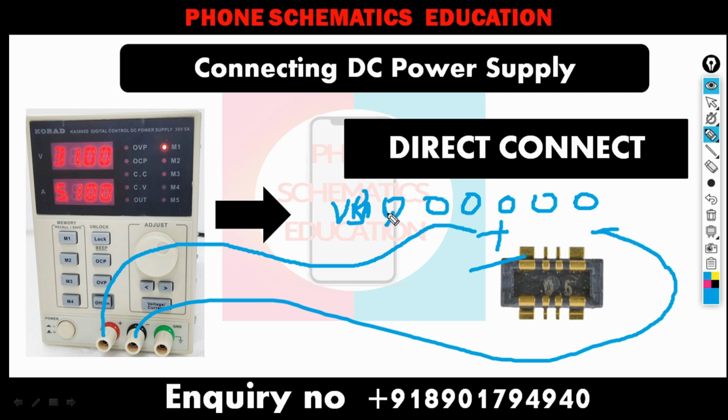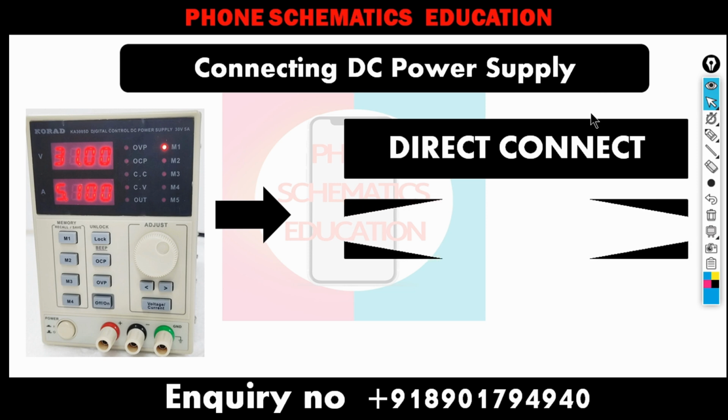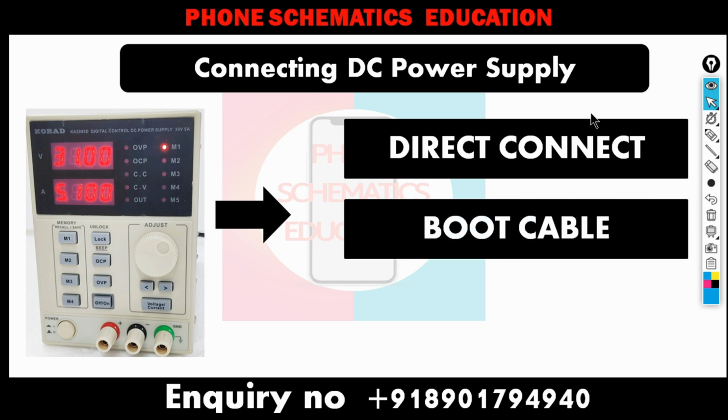So you can take a jumper from here, connect the jumper, and connect the jumper from outside with the positive line. And ground the black probe somewhere on any shield on the motherboard. After that, press the on off button and find the short circuit. I mean to say, diagnose the phone. So this is one way. But in modern phones, we use another way. I'm telling you, it is called the boot cable, right?